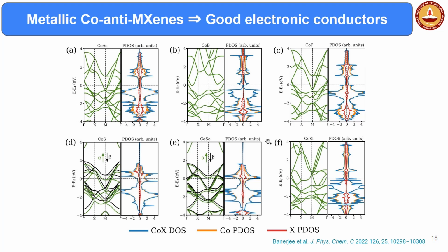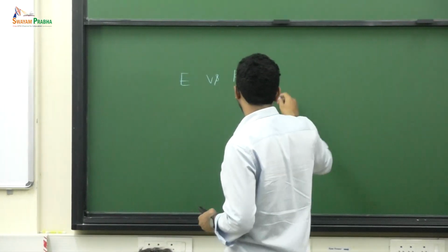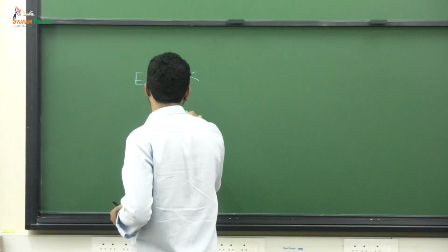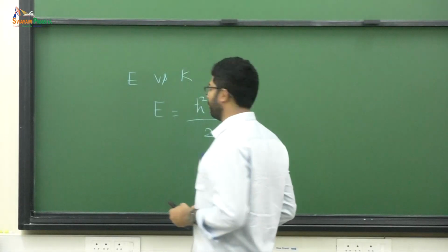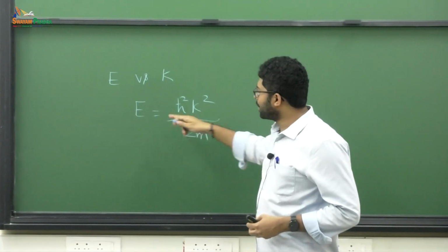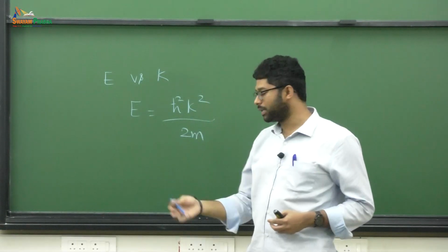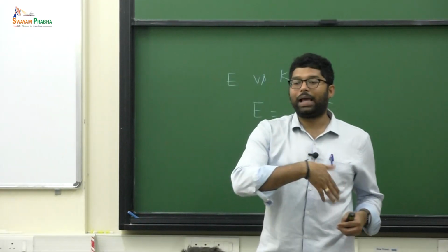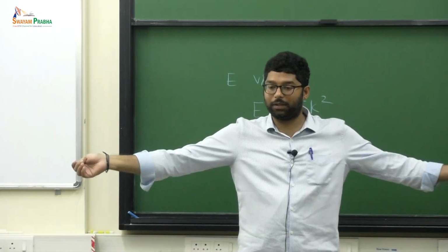So in this E versus k relation, what we are plotting essentially is E versus k. If this has a high curvature, the kinetic energy corresponds, as I said, roughly to ħ²k²/2m. So if the curvature, d²E/dk², which is what you would be calculating, is more, that suggests the electron's conductivity will be much better. That is a highly dispersed band, that's what it suggests.